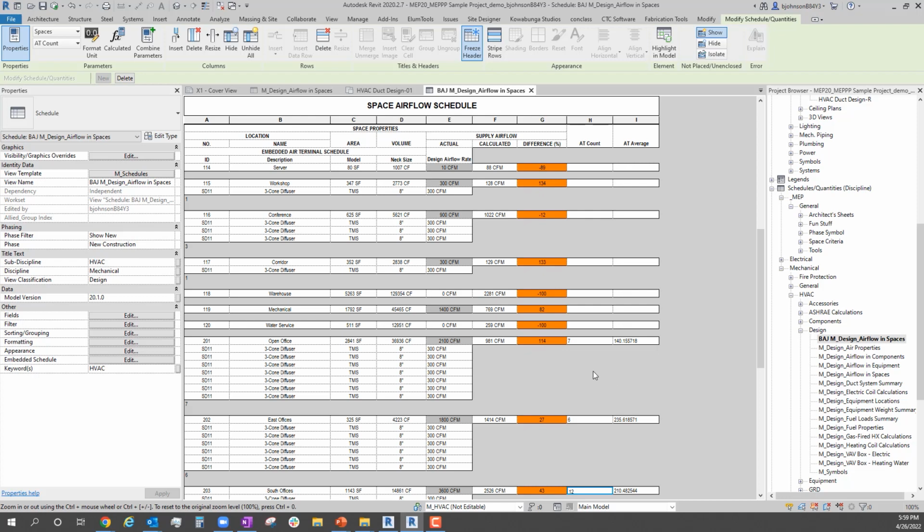In the pack, we also have Titus VAVs and Titus air terminals. So I would suspect if the lookup tables built into those are accurate, then my sizing routines inside of Revit may be more accurate than ever before. And therefore, when I do connect those up to my ductwork, I could have accurate sizing pretty close to what I need all the way to the VAV in every single room very quickly. If that's not the case, it's not doing the sizing correctly.